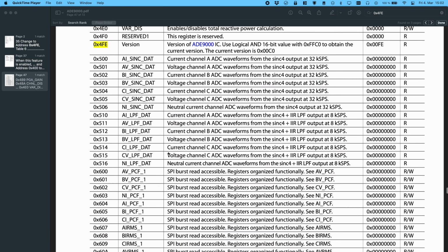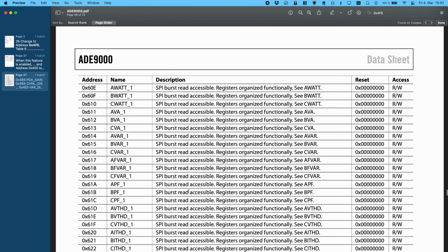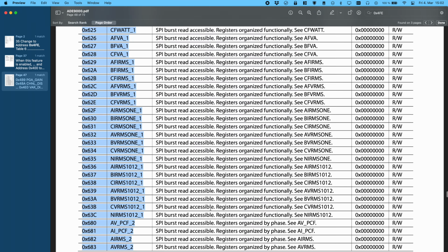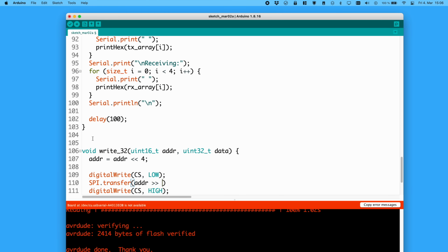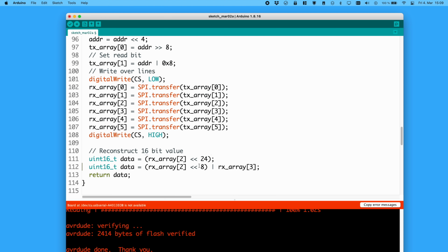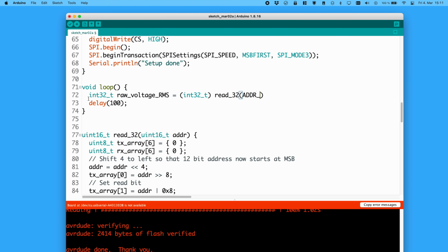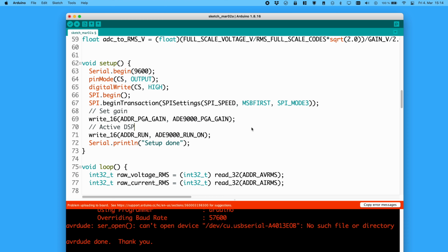Similarly to I2C, SPI devices typically also support burst write or read of registers, so that data of the next register address is sent after the previous one. But again, this is device specific and not related to the SPI protocol itself. We can now add a little bit of code to our demo setup to read actual data of the energy monitoring IC, such as the current RMS voltage and current of the mains.